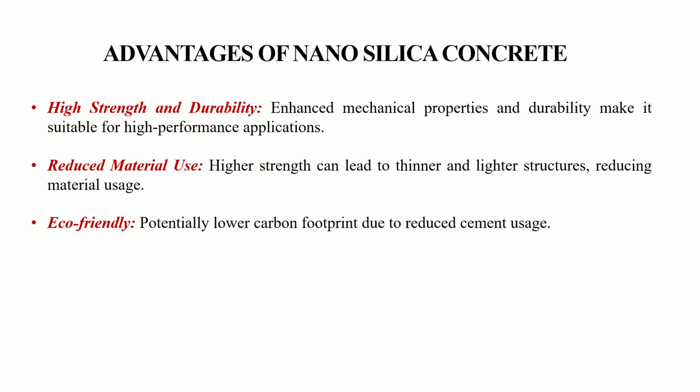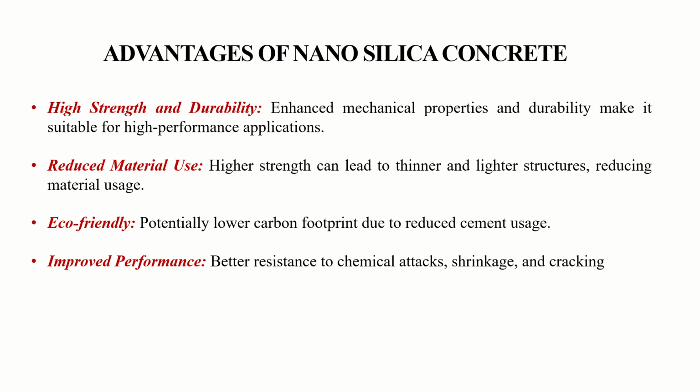It is eco-friendly up to some extent, because we are replacing cement to some extent with nanosilica, so carbon dioxide emissions can be lowered, which lowers the carbon footprint, and of course improves performance because of the denser microstructure. The resistance of your nanosilica concrete is better against chemical attacks, shrinkage and also cracking.